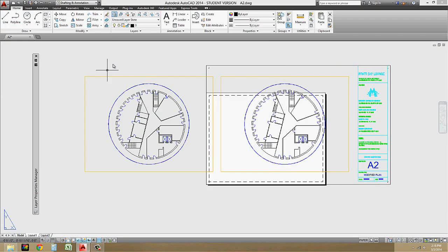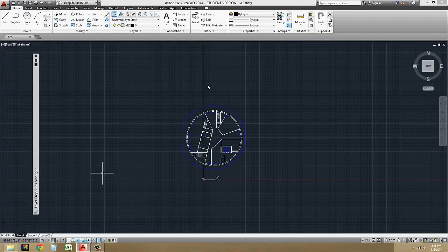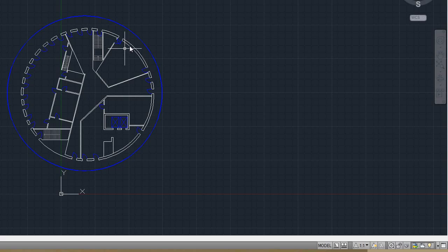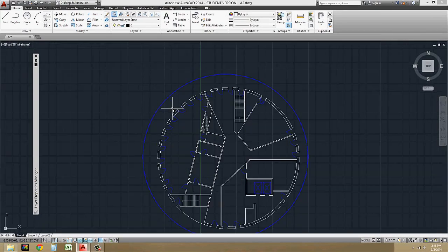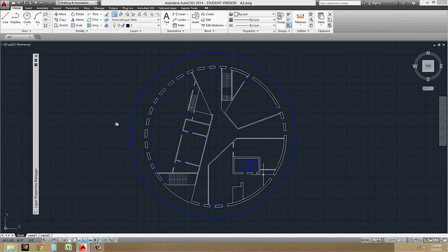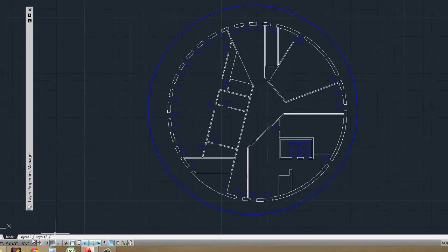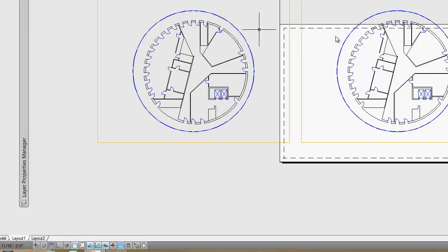So what AutoCAD did was make it a little bit easier in that I can go into my model file, or model space. This is my XREF, and I can use my layer freeze and my layer off tool buttons up here in order to make the process a little bit faster. Now if I do this in model space to the XREF, let's freeze those stairs. If I go into my layout, you'll see that they freeze in both of my viewports.